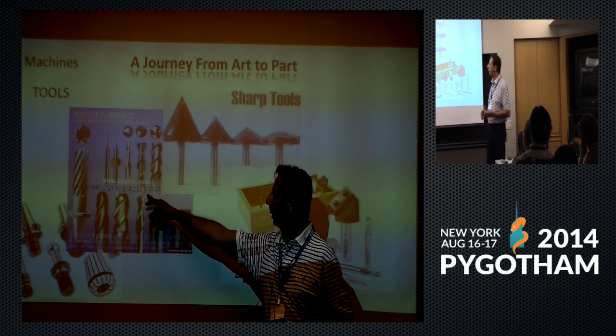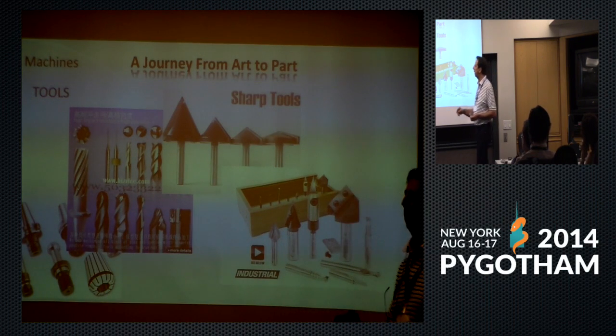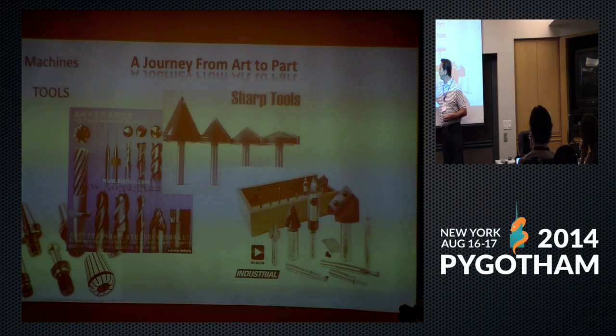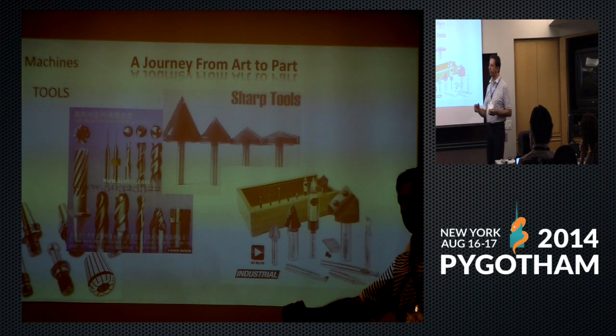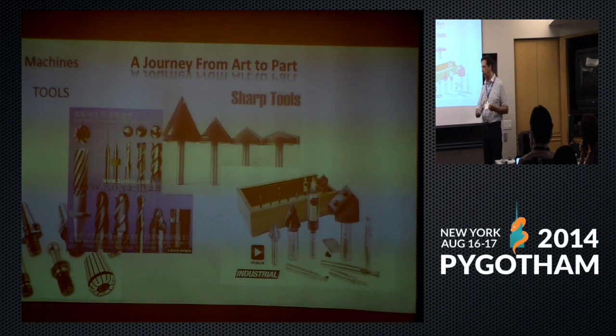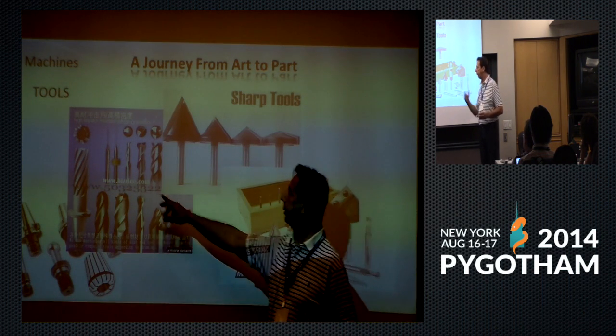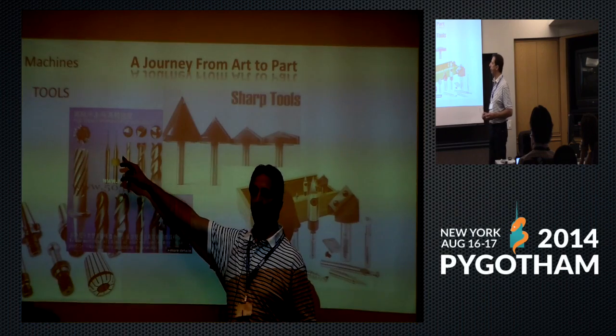Then if you carve things like that car, you would like to take a cutter which has a round tip, because the round tip eliminates traces of the hard edge of a square tip when it passes over round features. So there are different selections. I don't want to bore you with that.